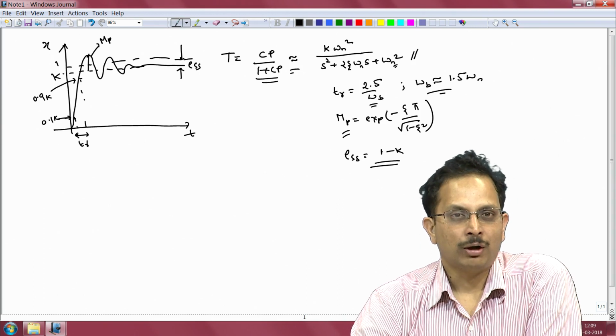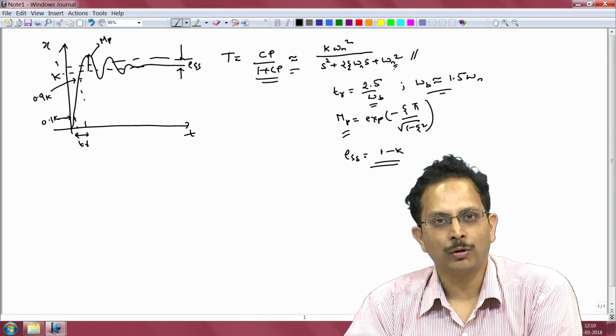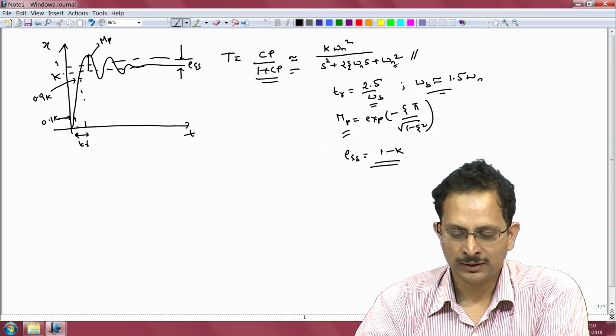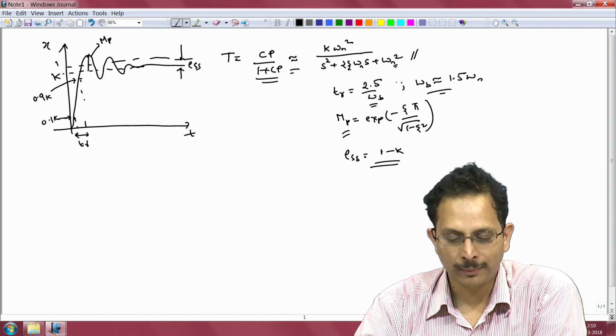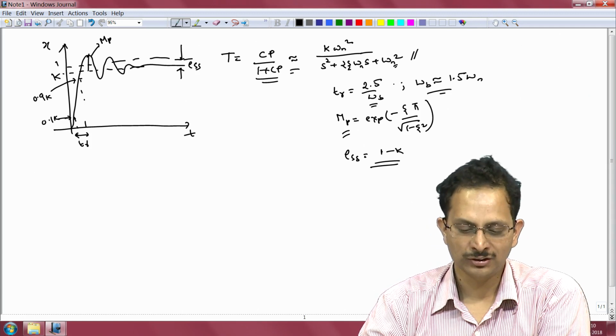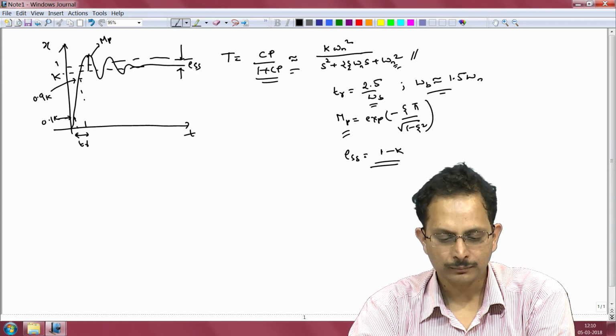Since we have decided to undertake design using Bode plots, we have to translate the closed loop specifications into corresponding open loop specifications. So, in other words, we should come up with the correct performance requirements on the loop gain, or the product of the controller and the plant transfer functions, that give us this approximate closed loop transfer function.